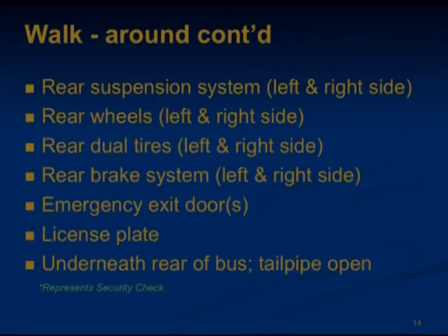Axle seals should not be leaking. Look carefully at the inner wheels and tires for evidence of wetness and check outside the center axle seal. On the rear dual tires, make sure they're properly inflated, not worn excessively, at least 2/32 minimum tread depth. Make sure that there's no damage or defects, and that the valve stem and cap are present and not leaking.